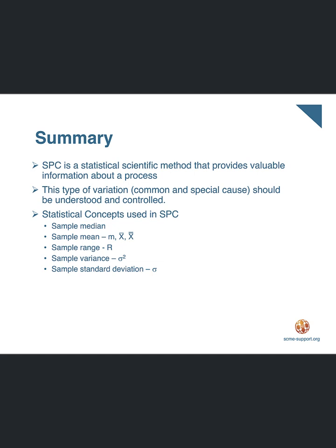It is easy to create a SPC chart with upper and lower control limits, with which to monitor a specific variable or attribute of a process and the variation of the variable or attribute. You can then use Shewhart rules, which are standard rules used in industry to help with the identification process.